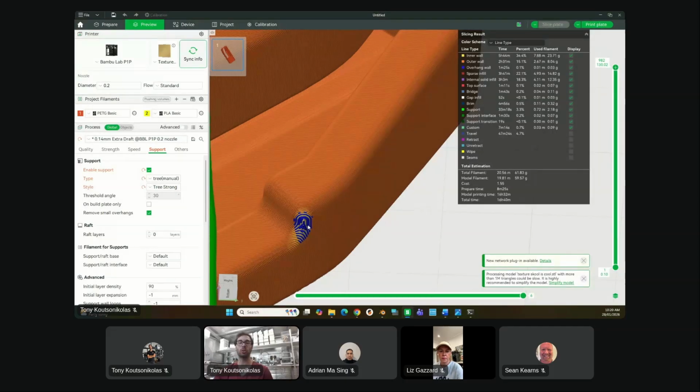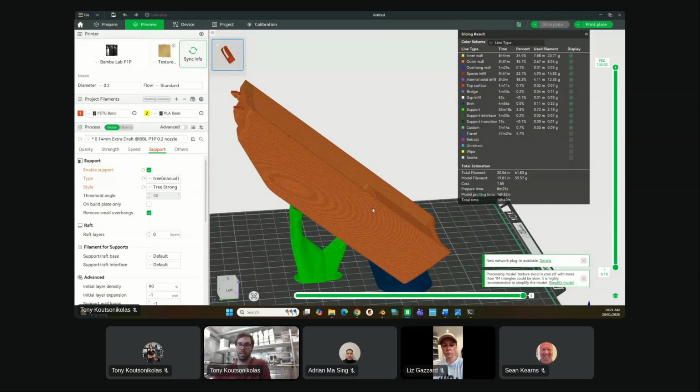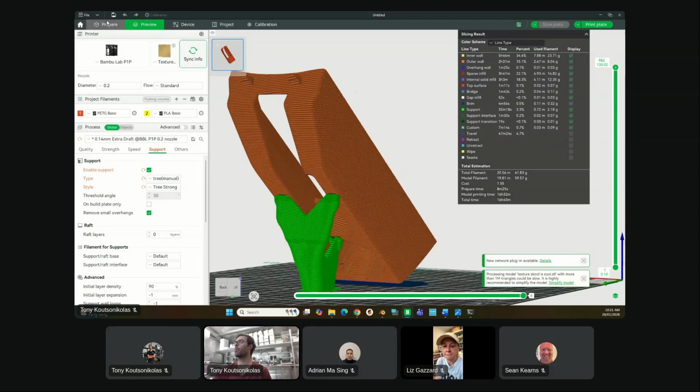Now, this actual part someone designed, right? And if they were designing it for 3D printing, you can change the surface here to be less of an overhang. That's totally plausible. And it wouldn't even look bad. You just slightly change this offset to get rid of this overhang. Totally doable, especially if you're redesigning this part, and it'll still look original. With the slight change in curvature you won't be able to notice it much with your eyes. So that's one way that I check for overhangs.